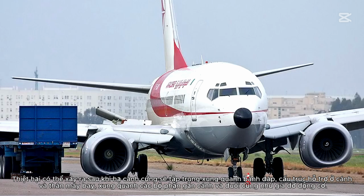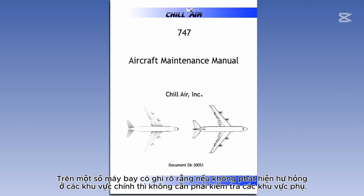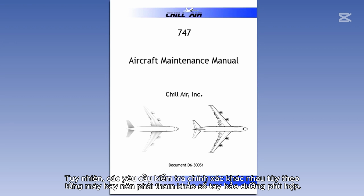The damage which may be expected following a hard landing will be concentrated around the landing gear, its supporting structure in the wings and fuselage, around the wing and tailplane attachments, and the engine mounts. Secondary damage may be found on the fuselage skin and structure, depending on the configuration and loading of the aircraft. On some aircraft, it is specified that if no damage is found in the primary areas, then the secondary areas do not need to be inspected. However, the precise inspection requirements vary from aircraft to aircraft, so reference must be made to the appropriate maintenance manual.